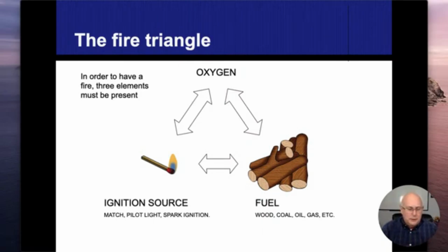Everything has what we call a flammable limit. So there's a lower flammable limit and an upper flammable limit. In other words, if I had natural gas and I was in 100% gas environment and I didn't have any fresh air in there at all, and I was starting to put sparks inside that gas, it would not ignite because I need to have that oxygen. I have to have the right mixture. I have to be between the lower flammable limit and the upper flammable limit.